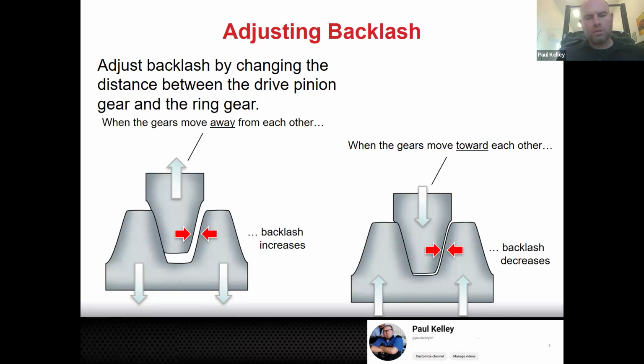So how do you make it less? Well, either A, you make the tooth fatter, and you can't. So instead, if you look, you bring it down. So here you go. You ready? You can do this. You could do this at home. Voila. This is kind of loose right here. Too much backlash. You want to tighten it up? Oh, too tight. Right in the middle. Right in the middle. Makes sense? So it's all about this.